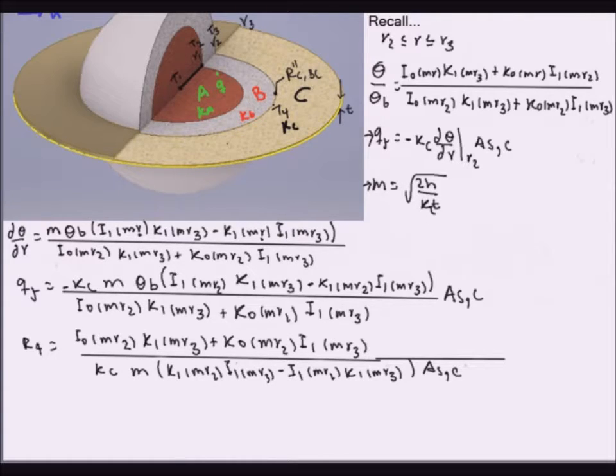And you may also notice that there is an m term in the denominator, and that m term also contains the conductivity at its denominator. But since it's the square root that we're taking, overall the conductivity will be cancelled out with that square root, and you will still have a square root of kc at the denominator. So it's still inversely proportional.